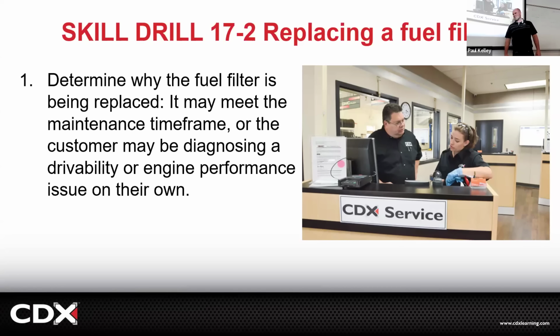Guess what? It wasn't junk in the fuel filter. It was a worn distributor shaft. Periodically the distributor shaft would move and it wouldn't make contact and it would lose spark. Then all of a sudden it would move back and it would get spark, right? So just my personal addition, people blame the fuel filter for too much. Is that put into context right? Fuel filter, fuel filter, fuel filter. Like, no, chill. That's not the problem. Let's look at some other things besides the fuel filter.